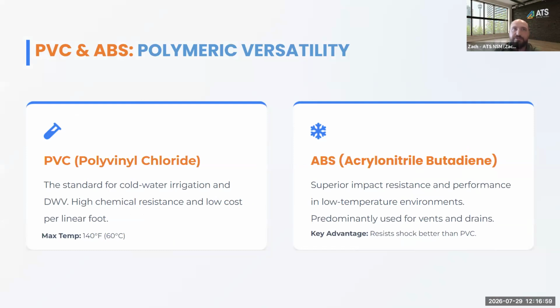Again, it's covered in more detail in the previous presentations, but obviously PVC reacts quickly to high temperature spikes and can lead to expansion and contraction that will be affected, and obviously supporting it appropriately and following the manufacturer's installation instructions is critical for that, which is going to give you the linear feet needed for each support, and also the max temperatures.